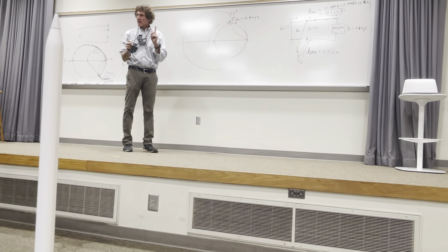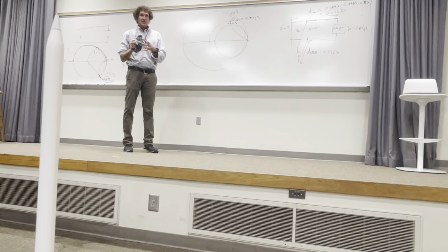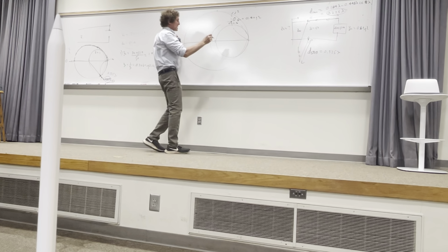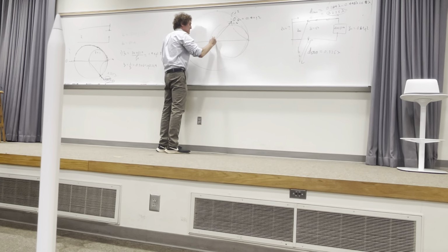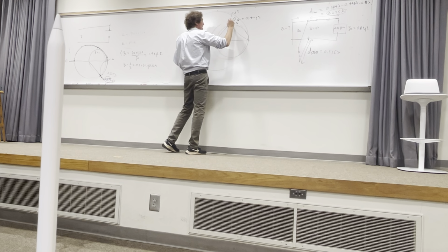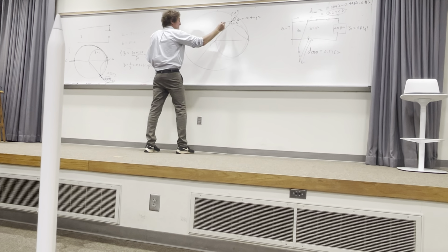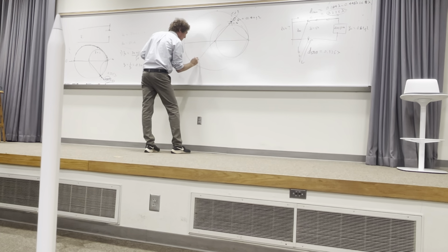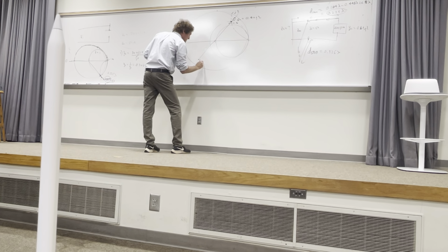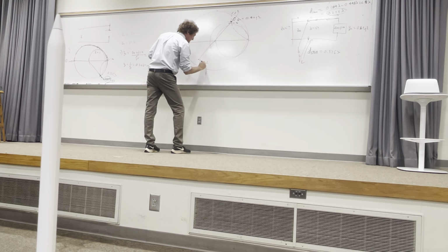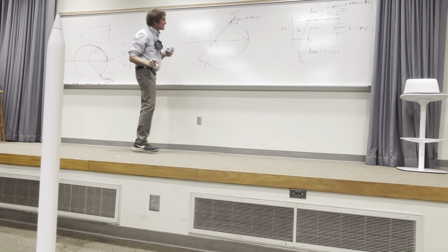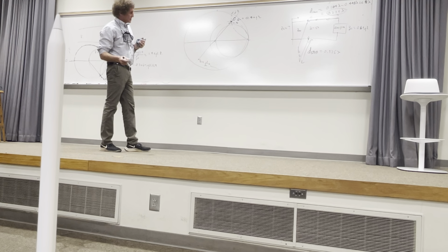Okay. Now, after that, you take your compass. Actually, I don't think you're going to need a compass. You're going to need to get the reflected point here, YL, or conjugate point, which is 1 over ZL. If you can tell me what that is, just take 1 over 0.8 plus j2.